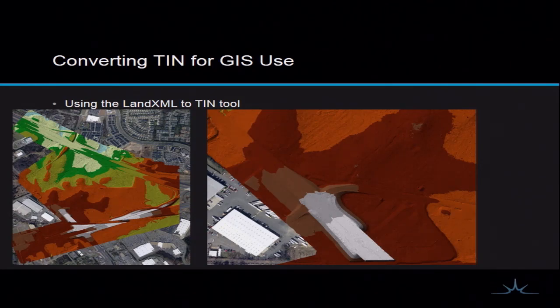And then a lot of times when we receive engineering files, I'm not sure if everybody's familiar with the Y lines and the L lines, but the main lines of the highway network, let's just say I-40, would be considered the L line. And for a whole project that's 12 miles long, they might not give us a whole TIN file that would cover that 12 miles. So they might give us one that covers the first 3, and then 3 through 6.